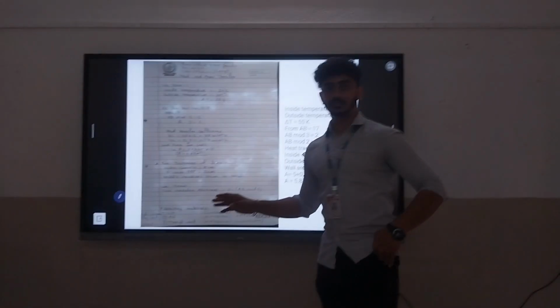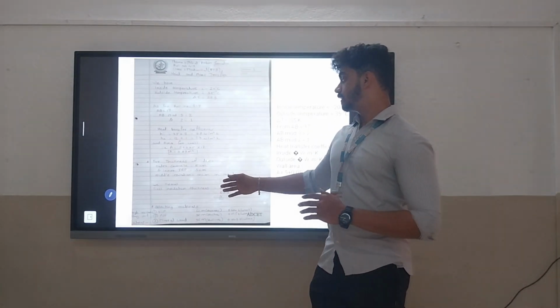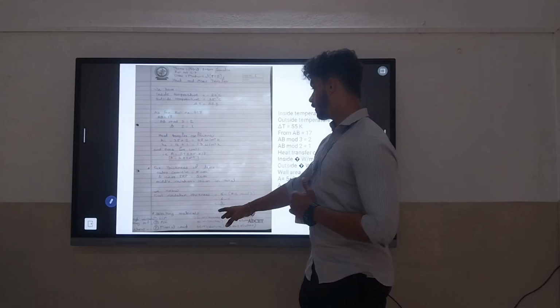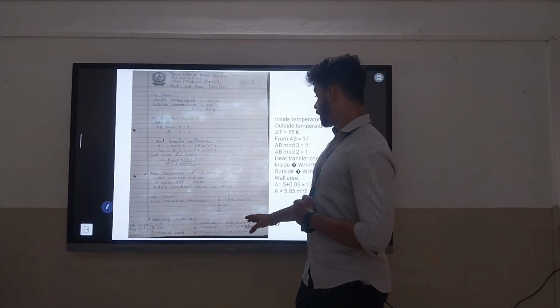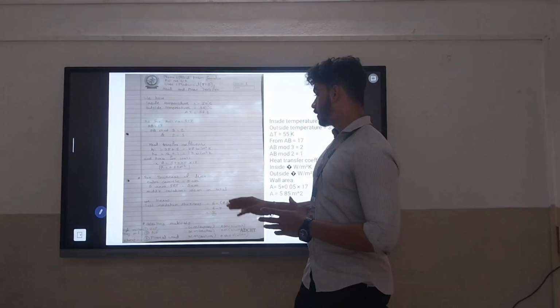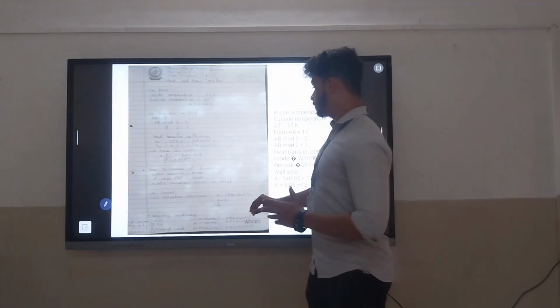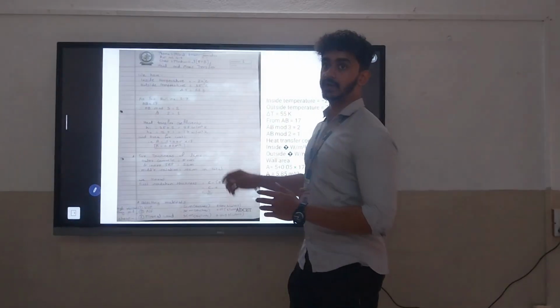Among these parameters we have to consider any 2 to 3 layers. So here I consider VIP layer that is 4 centimeter in thickness and has a resistance of 0.004. PUF is 3 centimeter thickness. So the total thickness becomes 20 centimeter considering the concrete and other blocks.